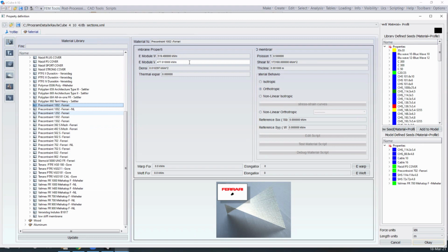When we use membranes, we never take into account the thickness of the membrane. So in any paper that you see out there where membranes are involved, in 90% of the cases, you'll read the stresses of the membrane as kilonewtons per meter or kilograms per centimeter, whatever you want, but never megapascal. Because the thickness of the membrane, we cannot change it. It's something related to the type of the membrane. So we just throw away the thickness and we think in terms of a force over a length. Okay, is that clear? It has to be clear because it's very important.